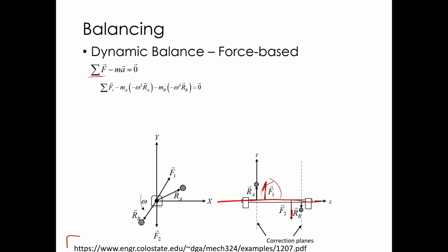That defines the sign convention for those forces. So this is the force on the thing you're trying to rotate, the force on the thing you're trying to balance, not the force your bearings would measure. The force your bearings would measure would be the equal and opposite of the force on the thing you're trying to balance. It's important. That's why things might seem to be opposite of where they should be when you put your balancing weights on. It's the force on the thing you're trying to balance, not the force that you'd actually measure.